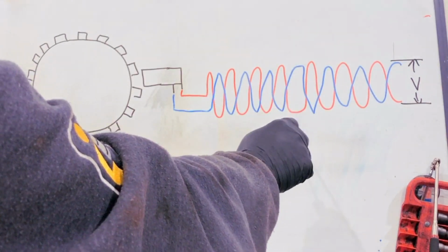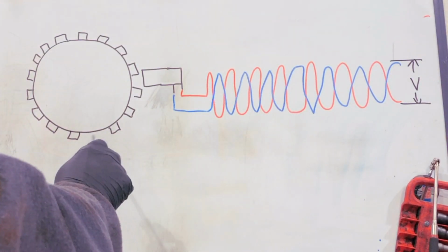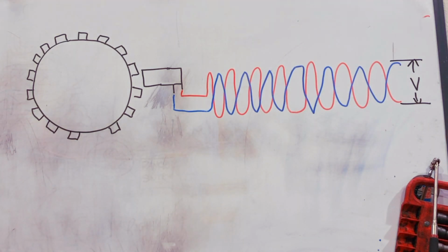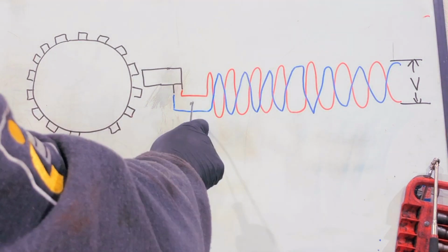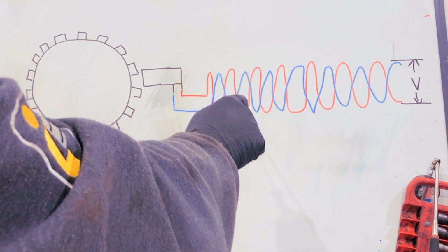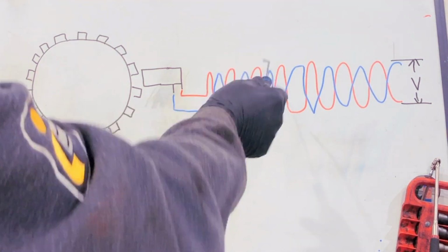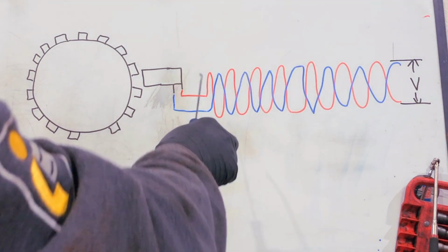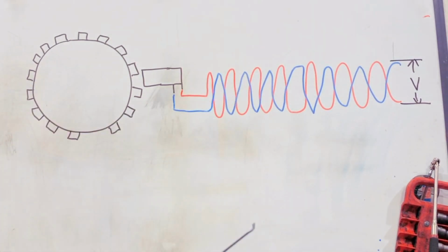As you can see, there's a gap here. This is where there's a gap in the teeth on the flywheel so that the engine ECU can determine the timing reference for the engine. So each side of this sensor will create a voltage, and the voltage should be equal on each side. But as one side goes negative, the other side goes positive. And what we're looking at is the amplitude of the voltage.